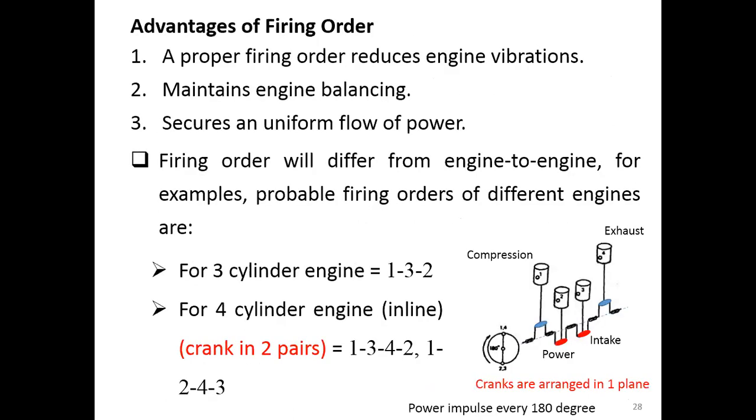The advantage of a proper firing order is that it reduces the engine vibration, maintains the engine balancing, and secures a uniform flow of power. So these are the reasons why we need a firing order for multi-cylinder engines.